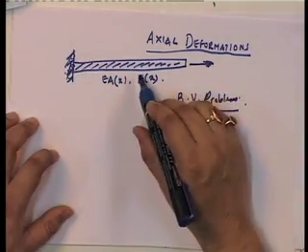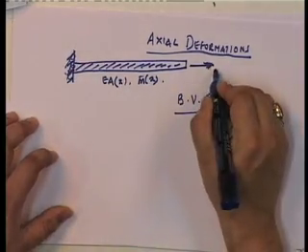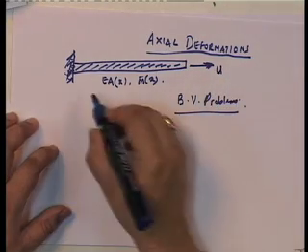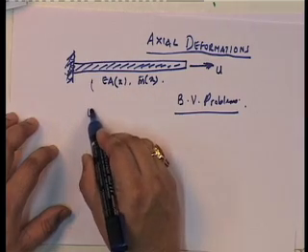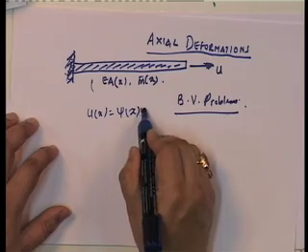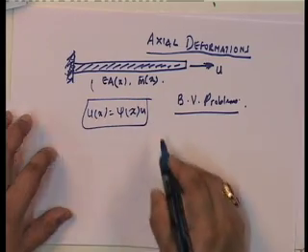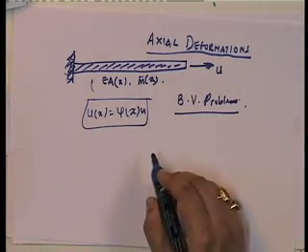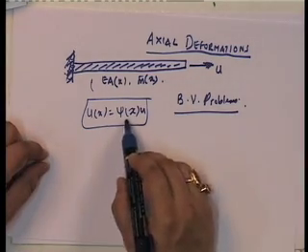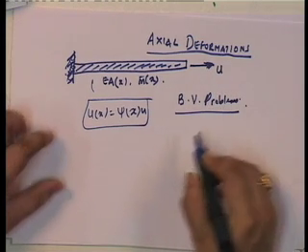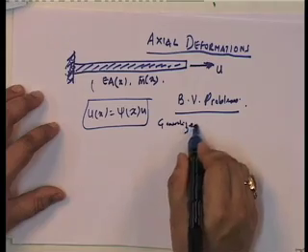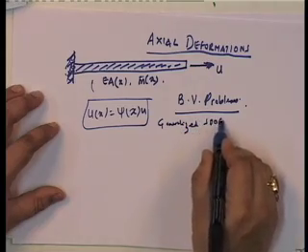Anyway, if I were to look at it from the perspective of a single degree of freedom, what would I say? I would say that this is my u, and u of x is given by some xi of x times u, and then write the entire equation in terms of xi x, and it will become a generalized single degree of freedom.